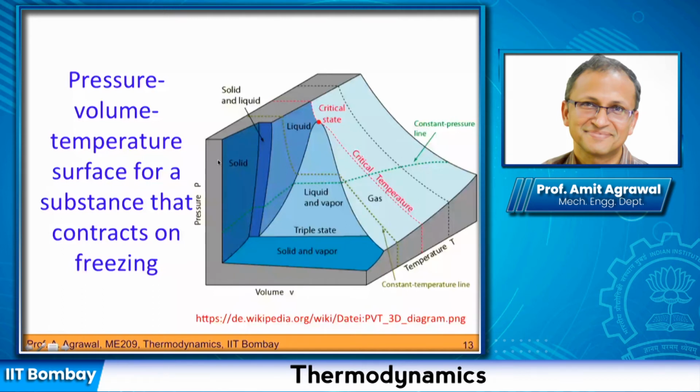So height is now being held constant. So you are essentially tracing this path, the green dotted curves, that's what you are going to see. And so you start off in the vapor region and we are trying to move towards a solid region. So you can see that, earlier we were saying that we are adding heat. In this case, you are removing heat, you are cooling down. So once you cool down, you again start from vapor, superheated.